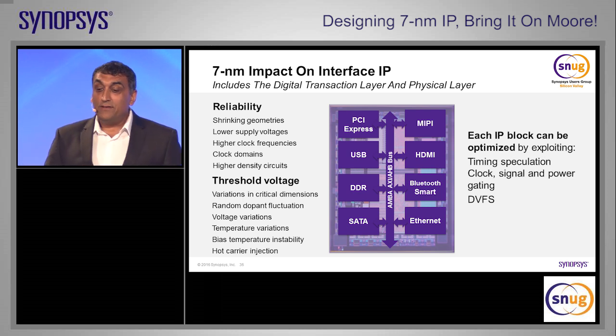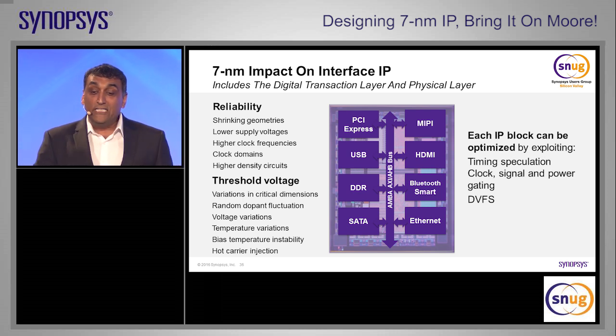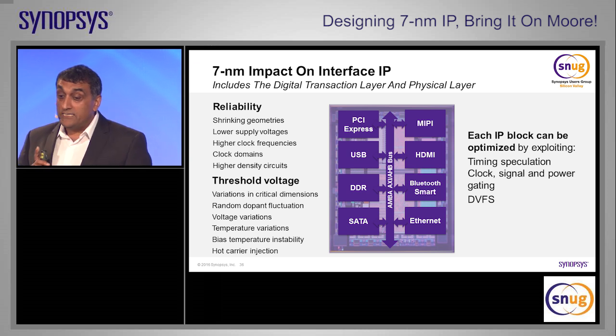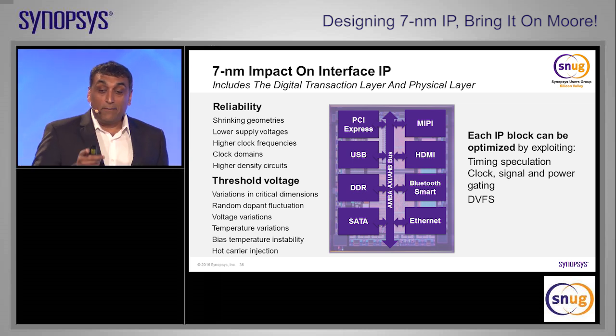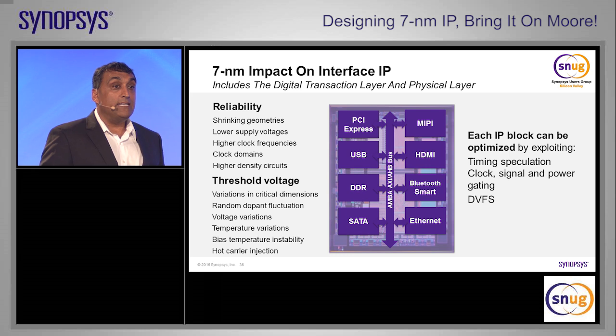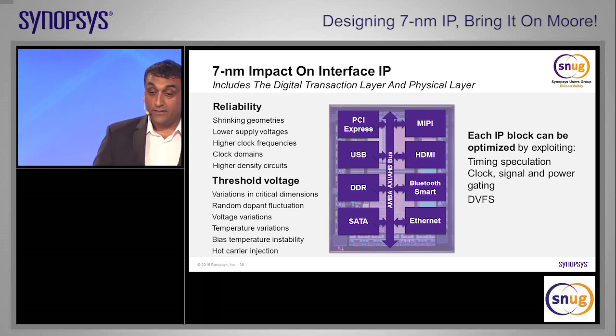the interesting thing with 7 is that you can optimize each of these blocks by exploiting timing speculation, by looking at clock, signal, power gating, and dynamic voltage frequency scaling. Okay.